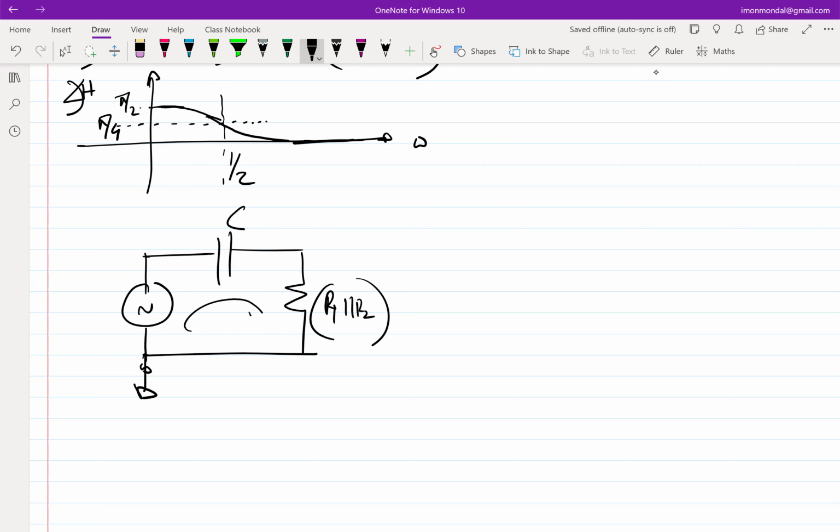the impedance given by the capacitor is much higher than the impedance given by the resistor. At very low frequencies, capacitor gives you high values of impedance with respect to whatever it is attached to. In a first order circuit, it is attached to a resistor. So if the capacitor is giving you much larger impedance, approximately what is the impedance that the source is seeing looking into this side? Is the question clear? It is only seeing the capacitor's impedance.